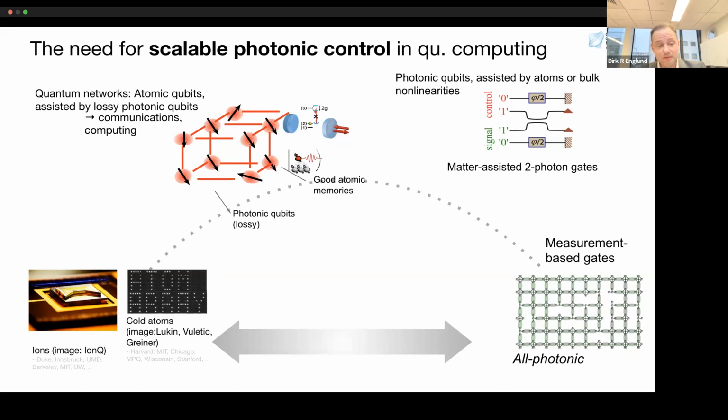Electro-optic modulators, when you buy them for telecom applications, might go to 20 dB if you're looking for the high-end stuff. But you need to go to 60 dB, right? And oftentimes just stringing one after the other isn't good enough. So it requires very precise multi-mode coherent control.